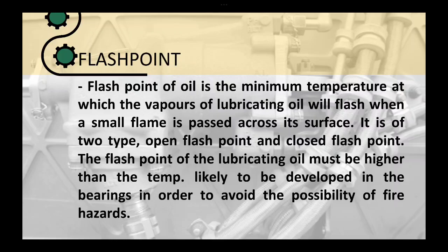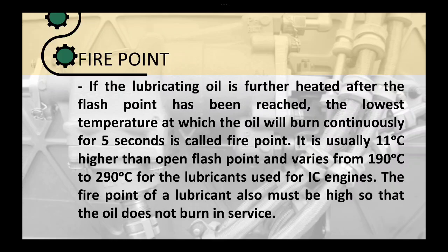Okay, that's flash point. While fire point is somehow related to flash point, at which your fluid will continuously burn for 5 seconds. Okay? It will be burning or last up to 5 seconds. That's fire point.